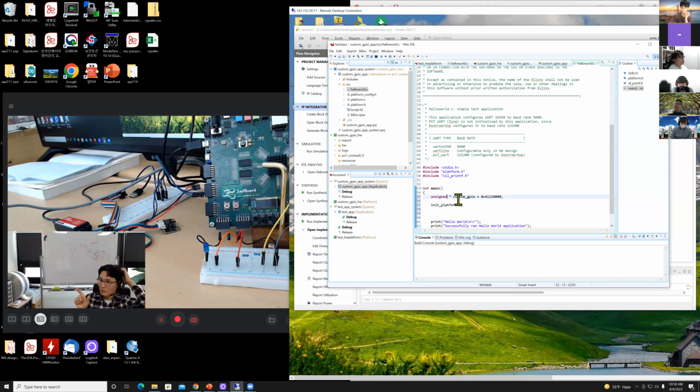It is pointing to the byte location. We have an 8-bit connection, so probably char would be okay, not unsigned integer. Unsigned char, how about that? This location is a pointer. Then before initialization, we don't want to execute this, right?